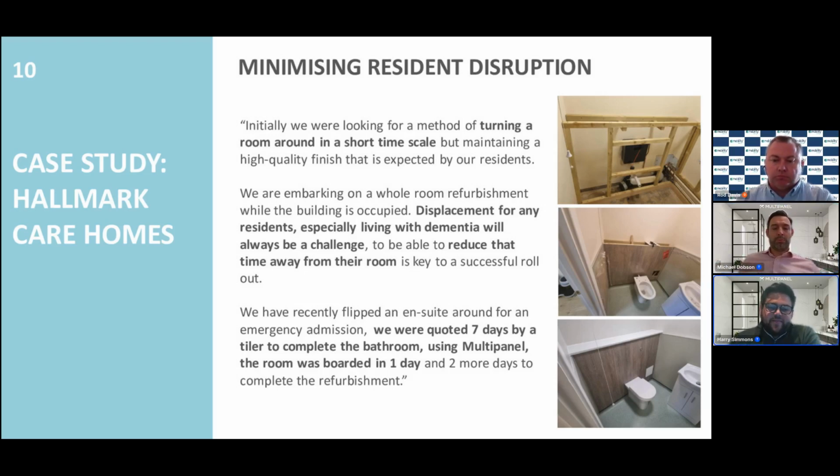Absolutely. So this page is actually a perfect example. The panels are fitted in the day and they finish the bathroom after 2 days, and the resident could use the bathroom the next day. If they were just fitting the panels that 1 day, all they've got to do is wait for the silicone seal to go off, and they can use the bathroom the next day. So you haven't got to wait for grout and adhesive and these things that are involved in tiling to go off. So yeah, back in the next day.